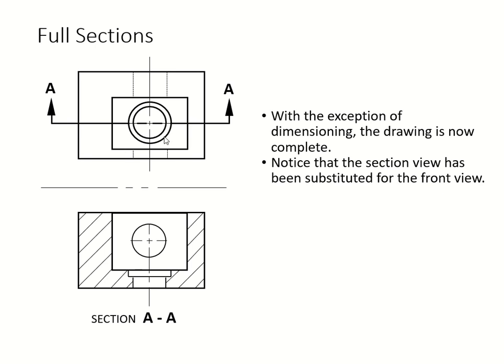Now we're going to put back the other removed section, but we're showing, oh hey, I cut it right there, and my front view is showing the section, which is this. You can see this section view on AA, which is this cutting plane AA, and I'm drawing my front view according to that, not from the front of the object anymore. Now this surface is inside of that object where the cut plane is.